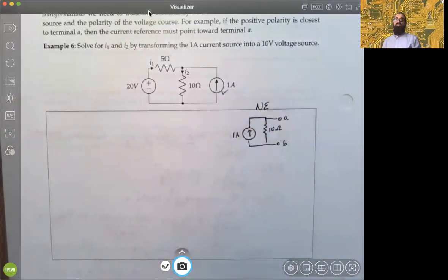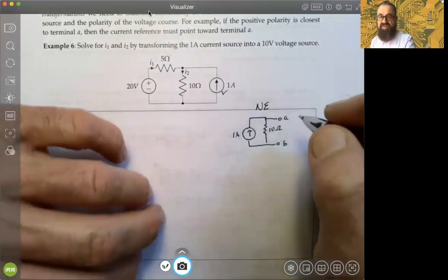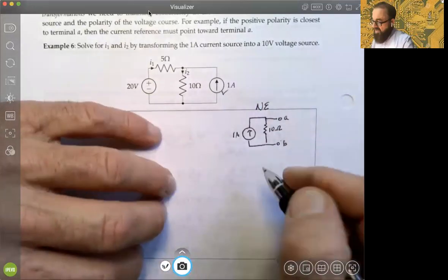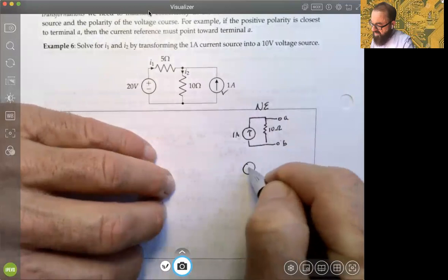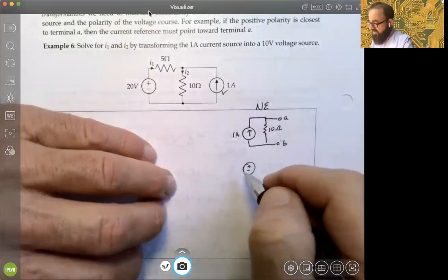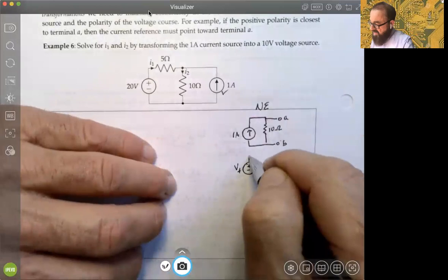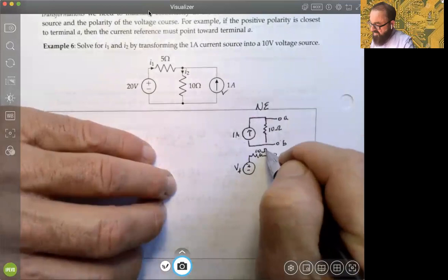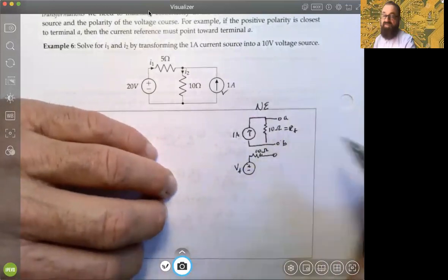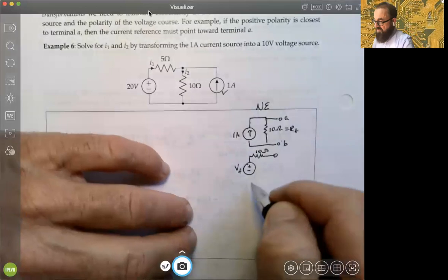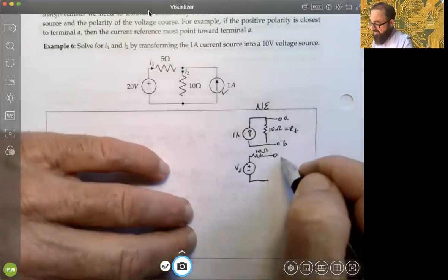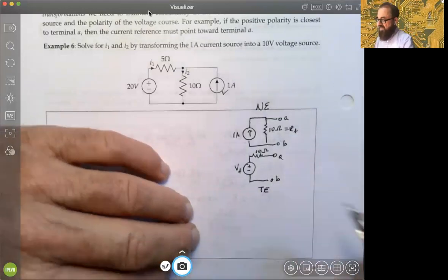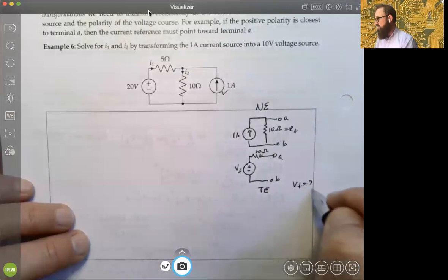What we need to do is represent its Thevenin equivalent and then replace this Norton equivalent with the Thevenin equivalent in the original circuit, right? So we know that the Thevenin equivalent will have to look like this, all right? There's the Thevenin voltage. And again, it must be the same resistance. So there's no calculation needed for the Thevenin resistance. This is R sub T, we know that, okay? So we have R sub T already there. The only thing that we've got to figure out, again, this is the Thevenin equivalent I'm doing down here, is we have to figure out what VT is, right?